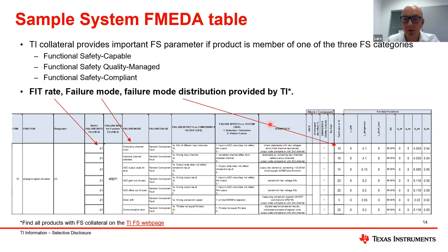So then we can do the diagnostics here. We can short detectable with test voltages, for example. And so we have the certain diagnostic matrices here, output comparison. Then we have to say, is it a dangerous error or is it a safe error? But since it's our A to D converter, it's a dangerous error. So any fault into this A to D converter can result in a wrong result.